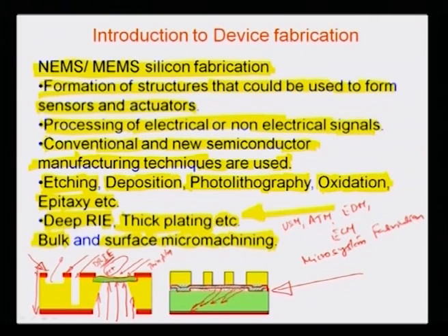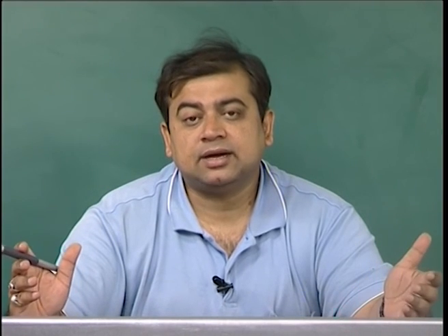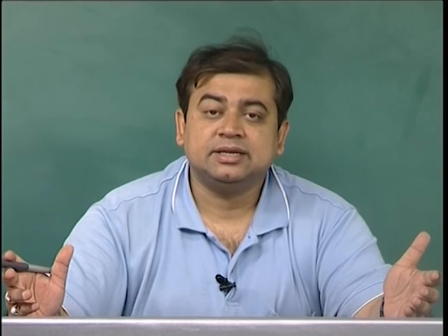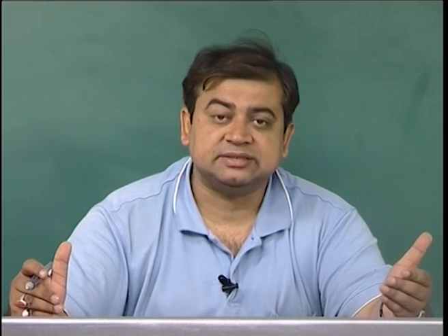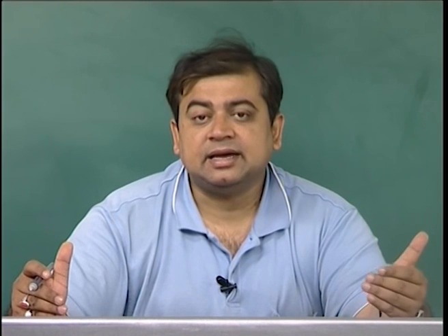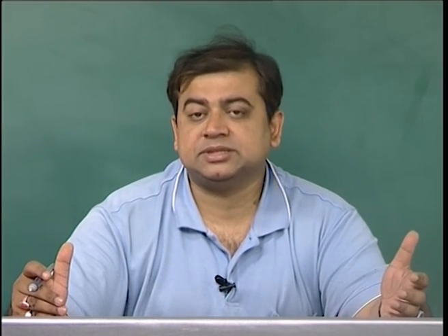Other examples could be deposition of these pillars and posts by using either metals or photoresist, where the structures so realized can be of some significance. For example, all the metallic interconnects in microelectronic circuitry are actually made using such metal imprints. It is called printed electronics, and it is again an additive micro machining process or a surface micro machining process.